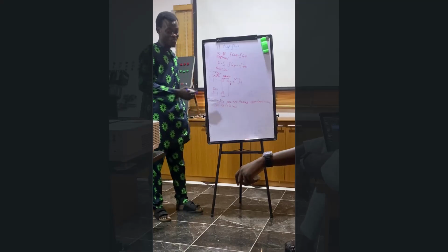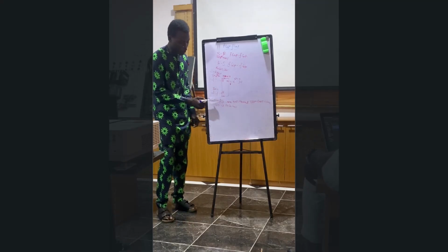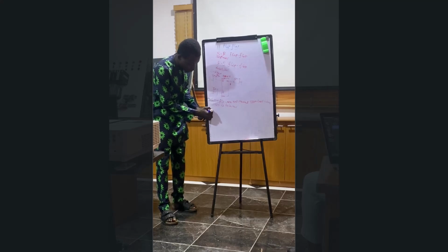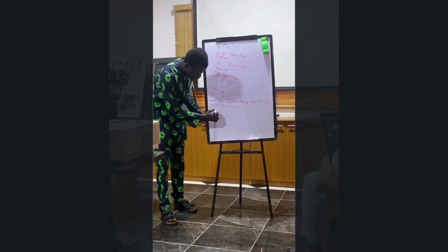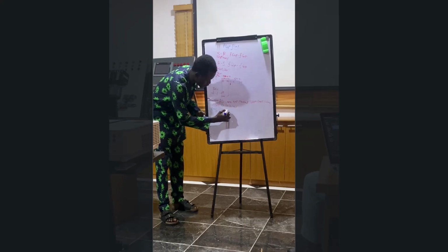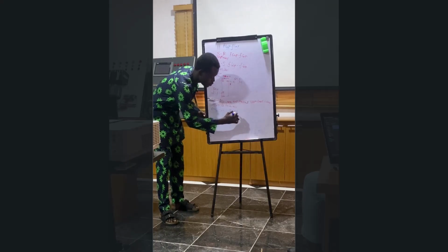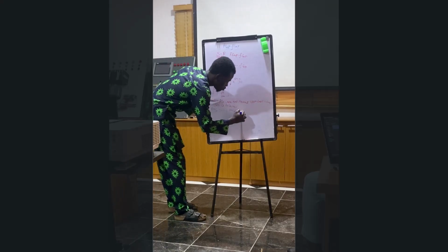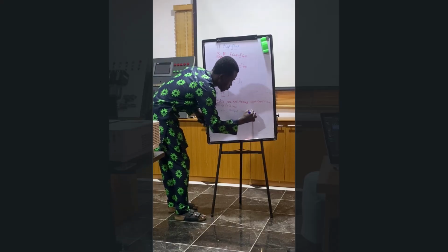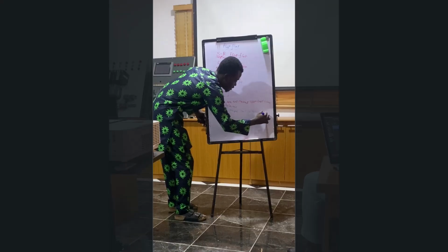Okay, so now in a situation where for this SR flip-flop, if only I0.0 is pressed, your output is set, that is 1.